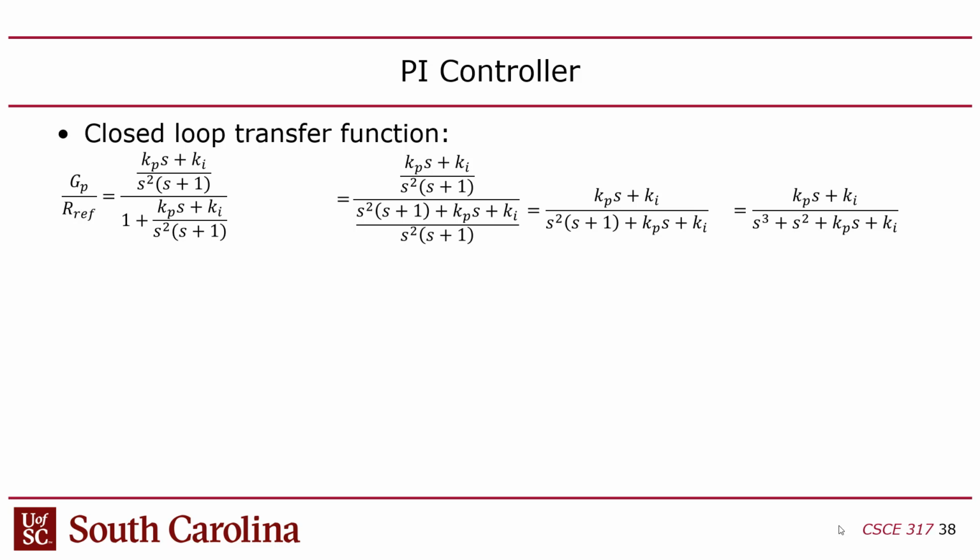Well, the way I did it, I came up with my own method, which is probably not a great way to do it. So I said, okay, what I want to do is I want to make sure the poles are negative, right? I want to basically engineer the poles. I want to put the poles of that transfer function where I want the poles to be. So in order to do that, I have to factor the denominator. The denominator is the key to the poles, right? Because you divide by 0, you get a pole. So if I have a polynomial, I got to factor that polynomial. And then once I have it factored, I can figure out where those poles are supposed to be.